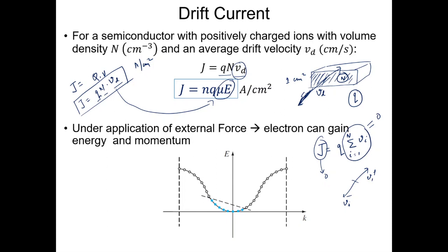Now let's assume that we are talking beyond random thermal motion. We have applied a certain field. Let's say you have now a force applied in this particular direction. The force could also be in the form of a certain electric field. If you have an electric field applied, then the carriers are going to be drifted in the direction of the electric field, or in the opposite direction of the electric field, depending on the charge of the carrier, charge of the particle, right? So if the net drift velocity becomes finite, the net momentum of the electrons will also be finite.